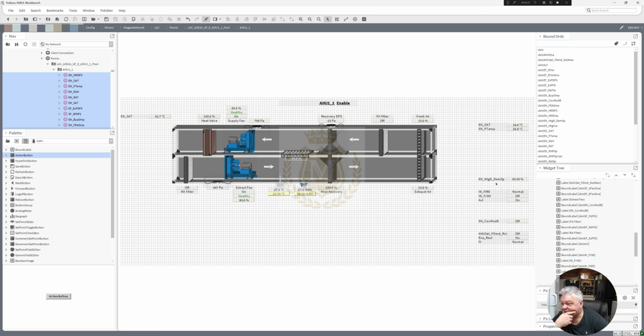Heating demand set point. So I'm looking to see whether they actually had a set point on that, and I can't see a set point for the heating demand. Only the return air and the humidity. No. Alright, we'll leave it there at the moment. Outside air, normal. Common fresh air intake.